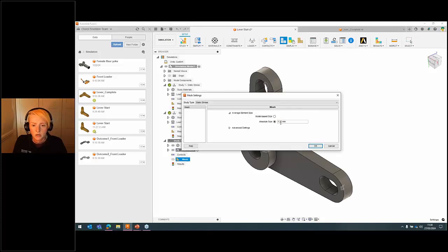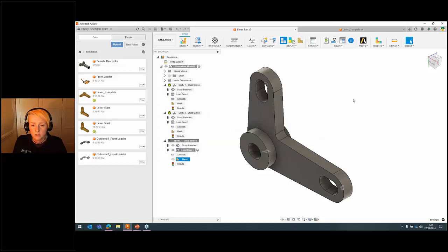We're just going to double check this mesh is 1.25, which it is. Fantastic. We'll just turn the mesh on. Yep, generate the mesh. I'm getting confused by the two of them, having them open at the same time. Okay, so that's the mesh generated. Now, what we can do with the mesh is create what we call a local mesh in just this one face.